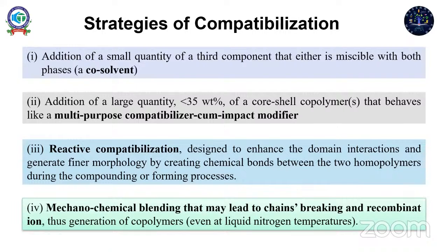Now there are different strategies of compatibilization. First is the addition of a small quantity of a third component that is miscible with both the phases, or a co-solvent can be added, or you can add a large quantity, basically less than 35%, of a core shell copolymer, which behaves like a multi-purpose compatibilizer cum impact modifier, or you can go for reactive compatibilization.